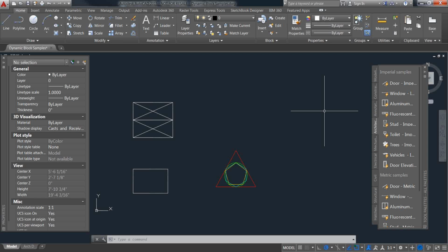This is a common frustration. When you're working in AutoCAD, a lot of people will run into this, that they have lots of blocks. They're authoring lots of blocks. They have a one-off situation, or as an example, they have maybe a vehicle block that sometimes they want to view in profile, sometimes in plan, sometimes from the front, or perhaps a toilet. Things like this where you actually might need to maintain 6, 8, 10 separate blocks just to show an object or a couple objects in different views. We can now combine those into a single block.